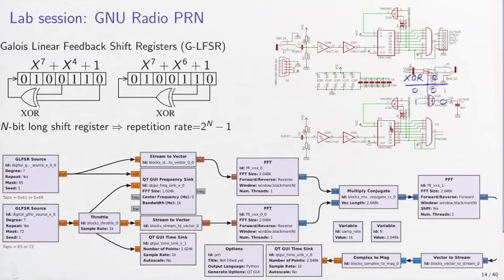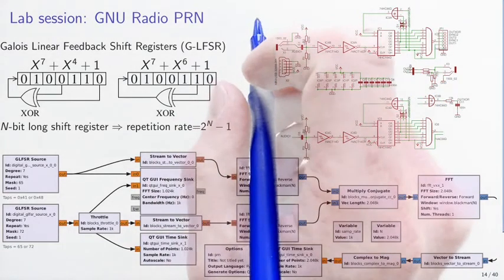This is repeated twice: one linear feedback shift register, and a second linear feedback shift register, and then the outputs of these two LFSRs must be mixed to detect the correlation. Again, remember the correlation is this function where we first multiply the two terms.